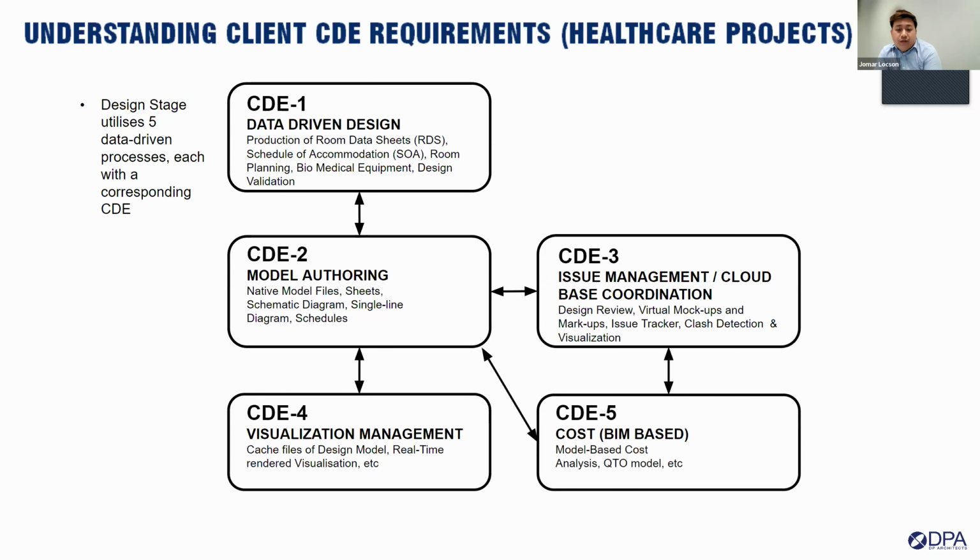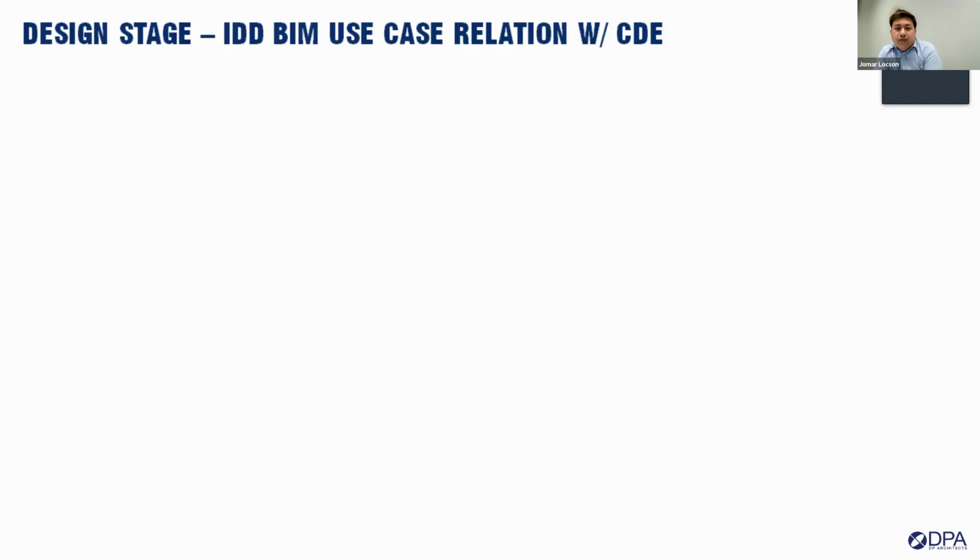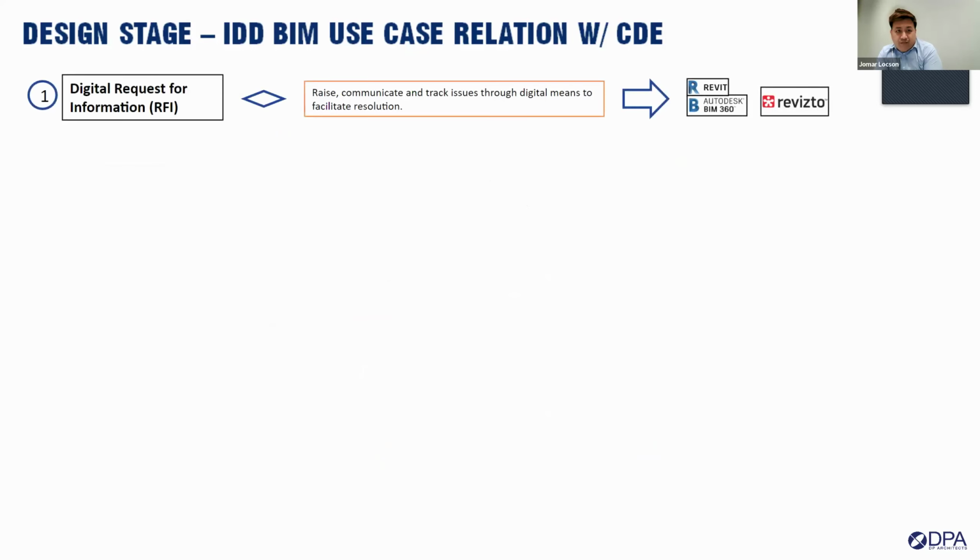And second but not least is to produce a BIM-based cost estimate from our BIM models. So entirely 100% using the BIM model to generate quantity takeoff. And plus is to have a content and asset management database, a centralized database for contents and libraries. So after we understand the CDE requirements, we also generate use cases in relation to the CDE.